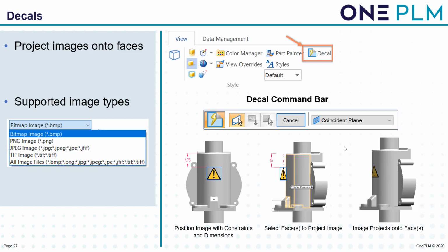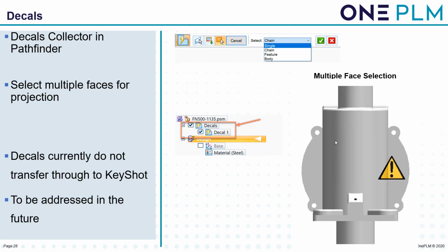There is an enhancement that they mentioned they want to make, so there's an option, same as in the surfacing, that we can wrap it onto the face rather than project it onto the face. So just be careful if you get a perpendicular edge. On that one, it would just go black all the way down the face. So you have to be very careful with that option.